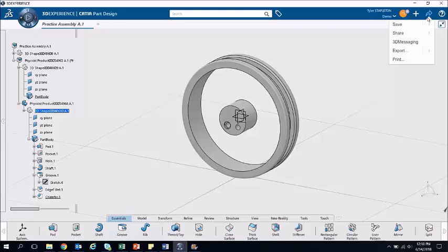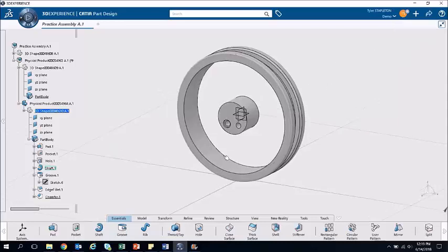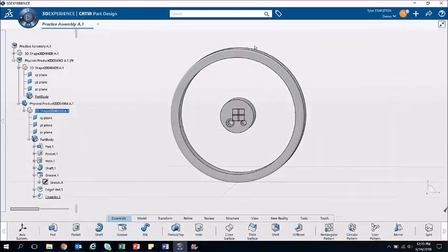This is very useful because it means you can make changes to your part without worrying about all of them becoming final in your model until you've decided you want to keep them. The other option we have here is exporting. I bring this up now because this is the best way to save a backup of your assembly. If you're worried about some changes being saved to your collaborative space that you'll want to undo, this is a great way to keep a copy of your model on your computer, just in case. This is also a great way to export your part to be used in another program like SolidWorks.